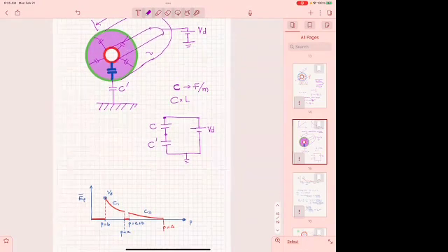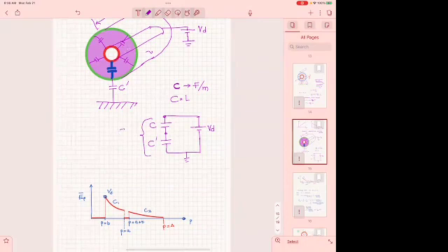What happens when you have two capacitances in series? Yeah, so the smallest one does what to your capacitance? It kills it, all right? A small parasitic capacitance in series with your own design capacitance eliminates it, because the total capacitance per unit length unfortunately now becomes the capacitance per unit length for the line, because the parasitic came unwarningly.